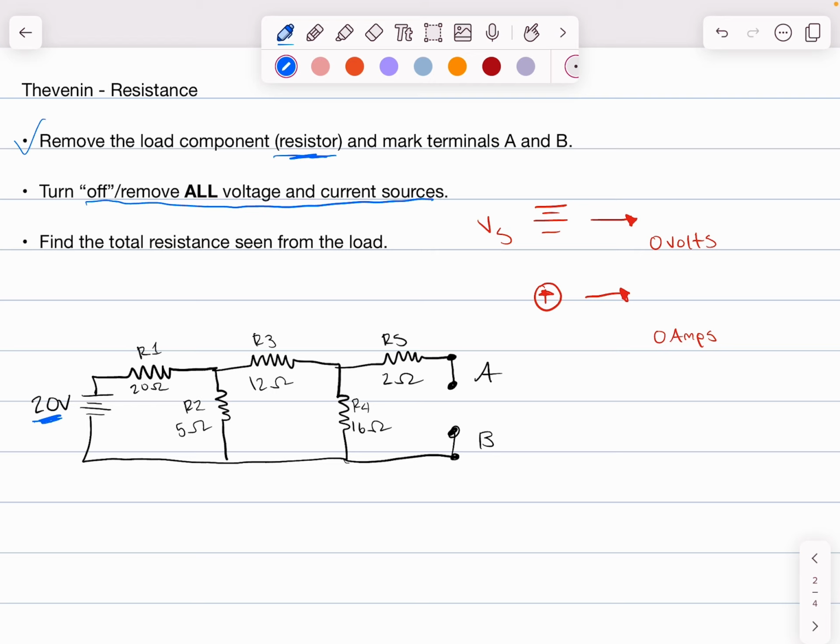And when we're working with this Thevenin resistance, we can think about what we've done practically in the lab. Whenever we measure resistance on our proto boards or in our circuits, we always have no voltage being provided to our circuit because we don't want that to mess with the reading. So if we want 0 volts across something, we know that this should be a short circuit or just a straight wire. So I'm going to go ahead and remove my battery.